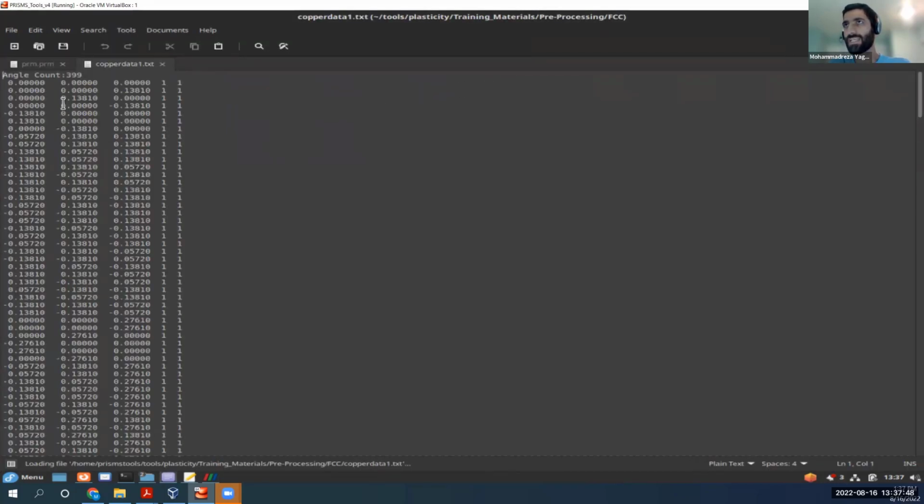So this is basically a list of orientations for each voxel that you would get from EBSD. And then for Dream 3D to read in that file, you need to have 2 columns with number 1, because all of the pixels in that EBSD have the same value or weight. So I'm using the unit here. And then that would be the input file for Dream 3D.